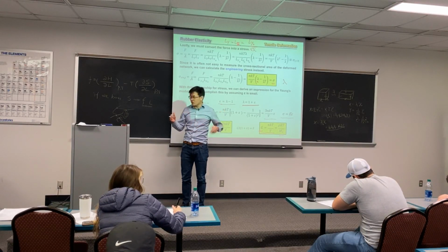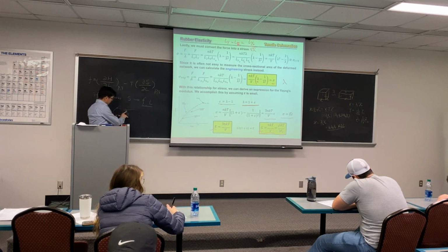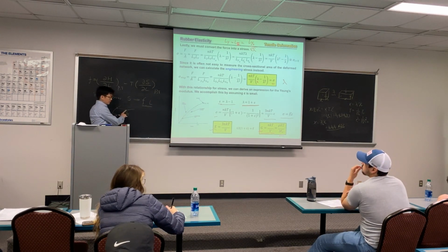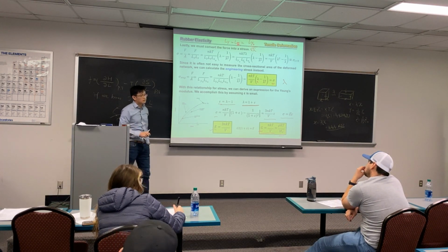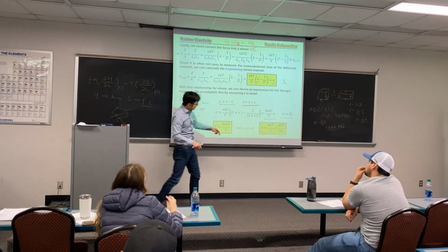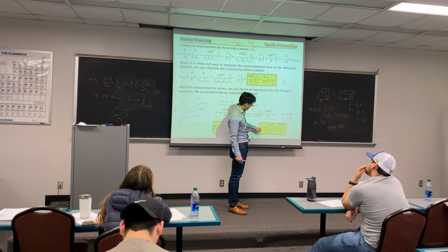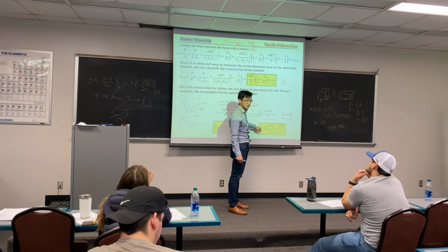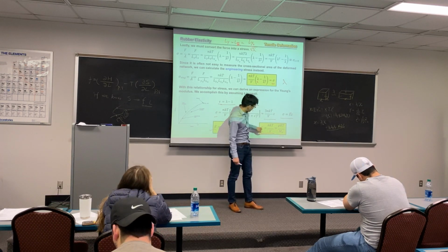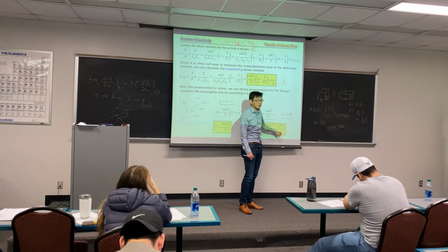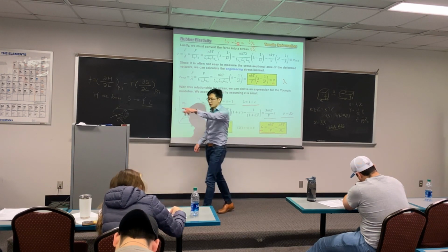If your volume is constant, we can describe this by the molecular weight between the cross-linked points. In this case, the number of strands is directly proportional to the shear modulus. But meanwhile, the modulus is inversely proportional to the molecular weight between the cross-linked points.